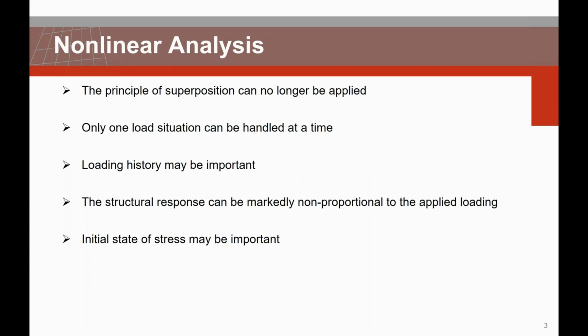Performing nonlinear analysis means that the principle of superposition can no longer be applied. For example, the results of several load cases cannot be scaled, factored, or combined as is done with linear analysis. Only one load case can be handled at a time.